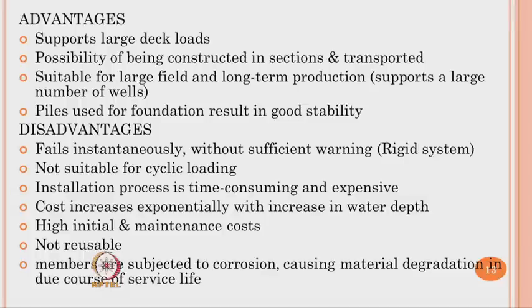There are some demerits of this platform. The platform will fail instantaneously without sufficient warning, because that is a general behavior of any rigid or brittle system. The platform is generally not suitable for cyclic loading, because any stiff system will have forces concentrated on the joints.